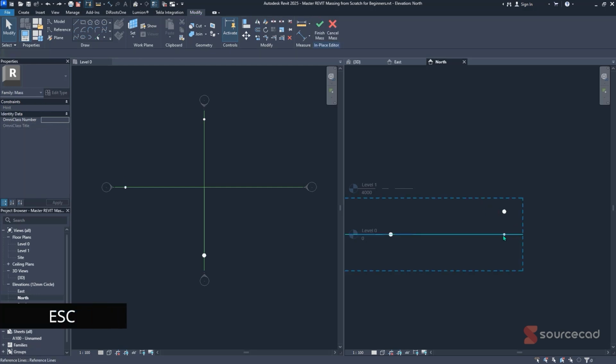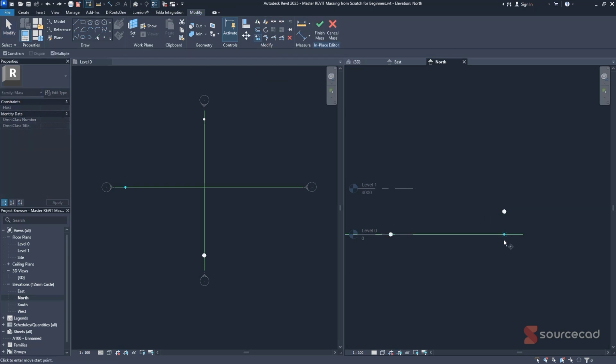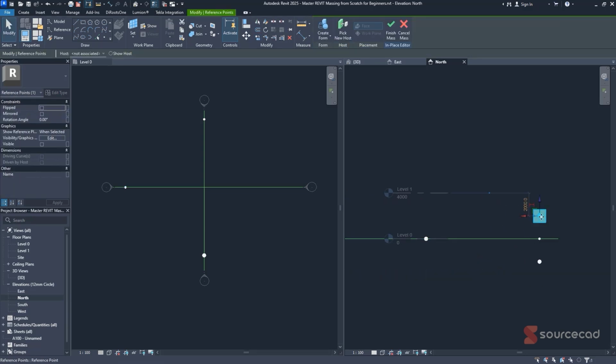So I'll hit Escape, then select this specific point element again, then hit Copy. I'll click on Copy from this specific base point, with my distance being negative 2000, or I can just click like that. After that's done, it's just a matter of placing it how I want. I can clearly see that I have 2 arrows here, but I can use this specific icon to move it within the axis that I am comfortable with. I can move it this direction or up and down, but I just want to use this specific item to come up with something that I am comfortable with, something like this.